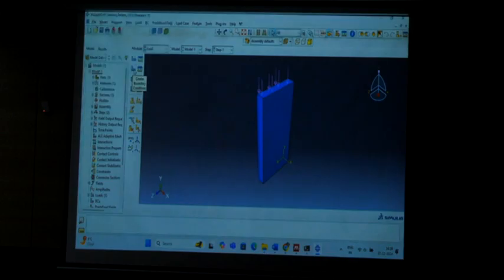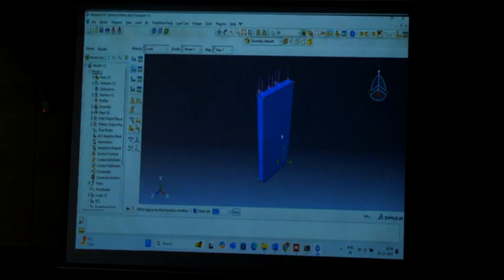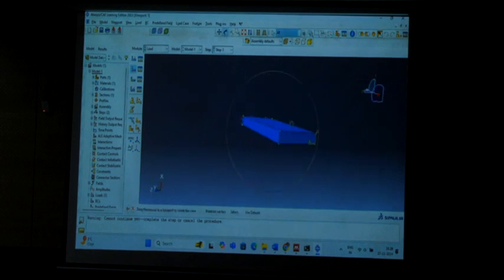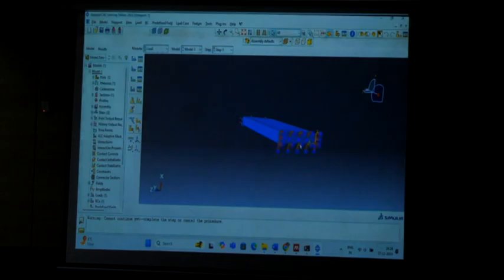Now we are going to create the boundary condition, that is a symmetry, since the sample is in symmetry. Then go to continue. Then it will ask you on which side. We give it on the side opposite to where we have given the pressure. I will choose this area and click on this. Here you choose how to give the load, whether equally distributed or in a single direction. Normally we go for the encastre, which gives conditions in all the directions. Since we have chosen a symmetry, click on OK. It will give you all the pressure in this direction.